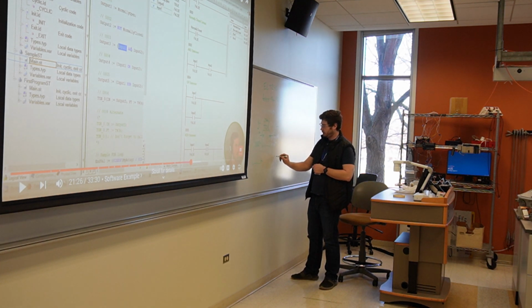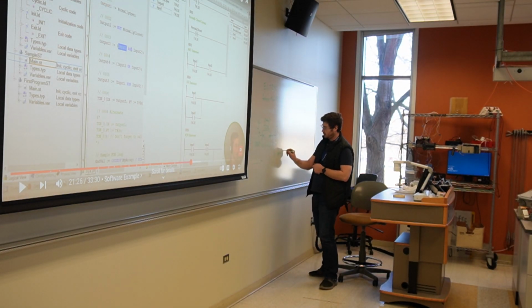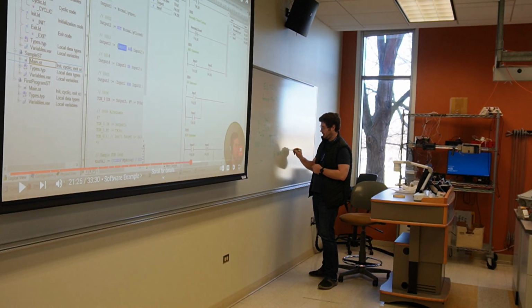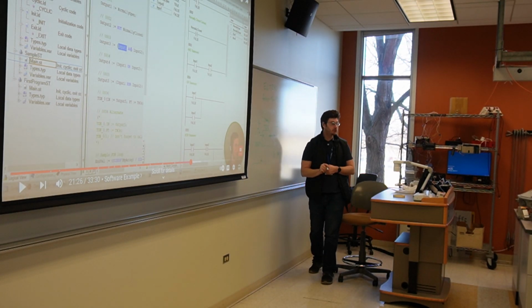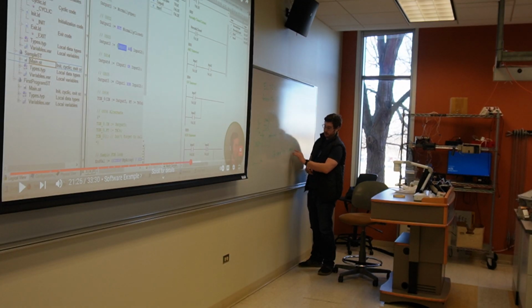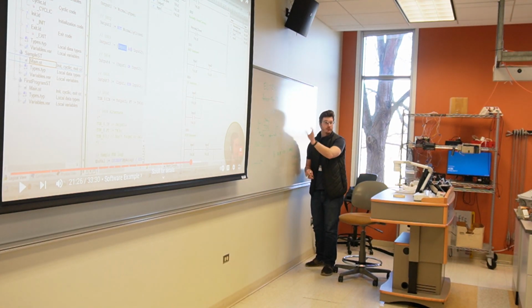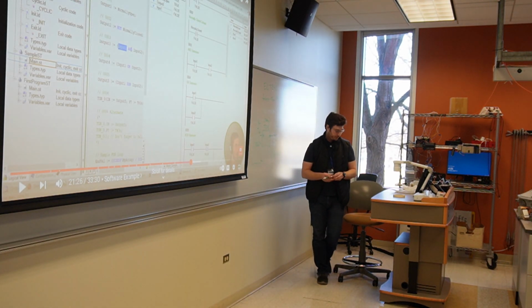For example, you could do A or B, and then parentheses, and then you could OR that with another chain of logic, C and D, for example. Then you have these individual ones. These will figure out, should this be a 0 or 1? Should this be a 0 or 1? And then those two will be ORed together for the final solution.